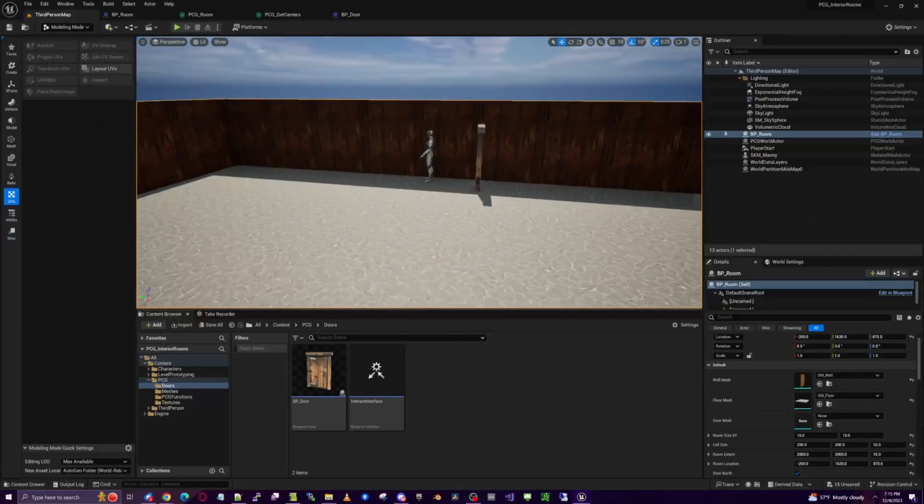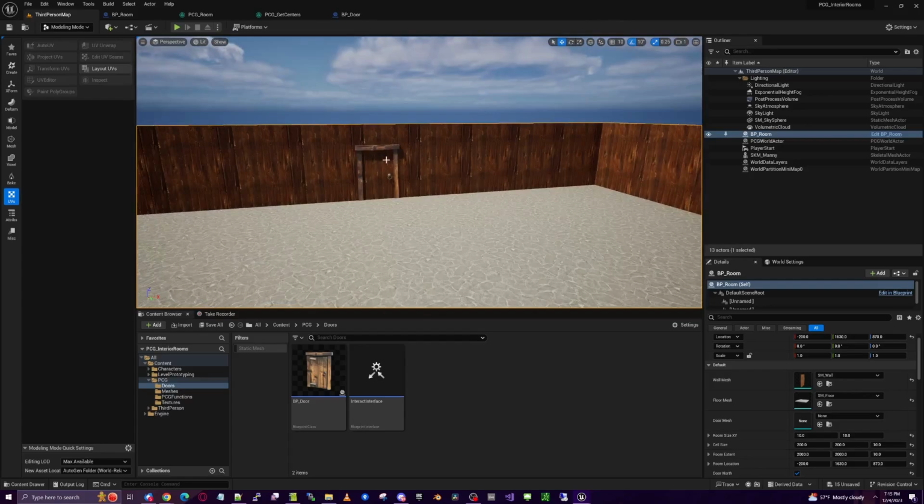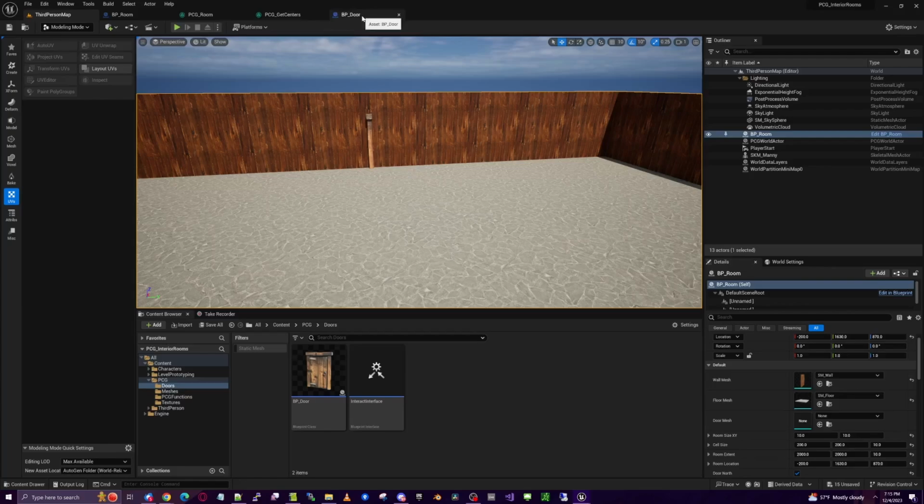We have a couple of problems here. One is that our doors are obviously merging with the walls and not cut into the walls. So we're going to have to create a wall section here that cuts out this door, but we're also going to have to exclude the door section from the walls. And then we have doors that are facing the wrong direction here. We can fix both of those issues.